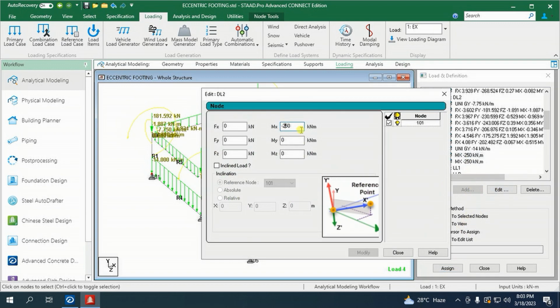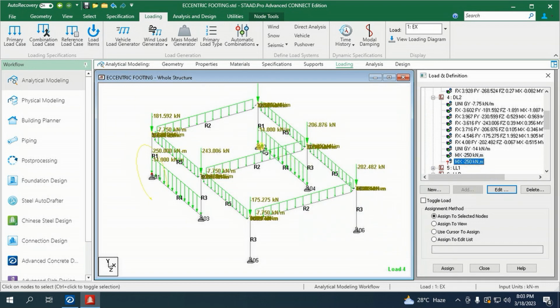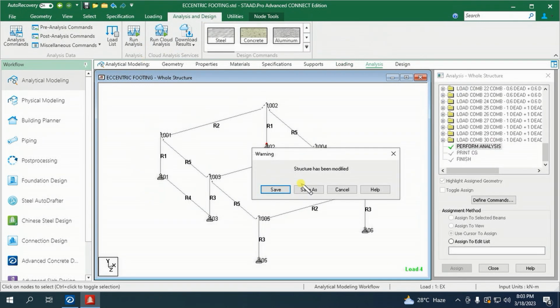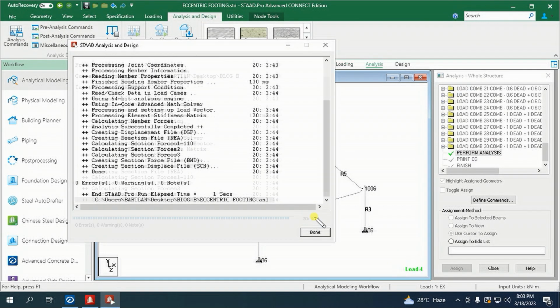The strap beams don't help in shifting the centroid of the structure because they are already stationary, and increasing their size will only lead to an increase in footing size, which we don't want. Unlike the grid beams, if the columns deflect either way, the grid beams move simultaneously.